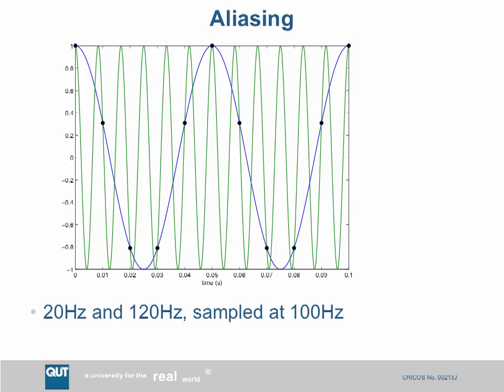If your sample rate's between 10 and 30 times the bandwidth, then you should use an approximation to the continuous time system, like that Padé approximation, for instance. If your sample rate's quite low with respect to your bandwidth, then you really should use the Z transform and the zero order hold. So these are some useful rules of thumb that relate your design methodology to the sample rate. And we've talked about why sample rate is really important. Any questions on that? Because I'm going to leave sample rate now and I'm going to get stuck straight into state space design and representation.